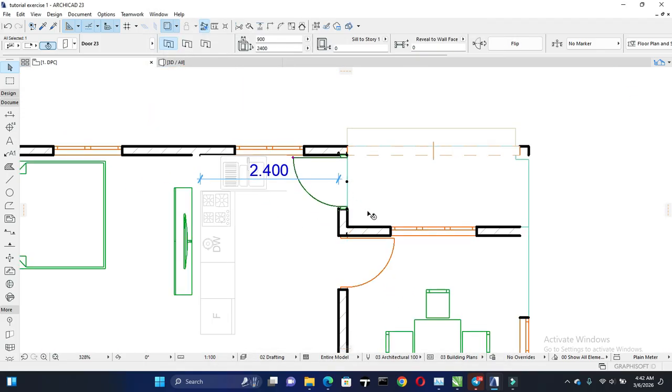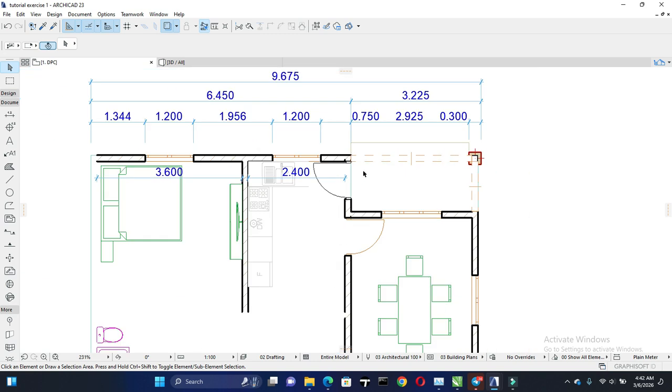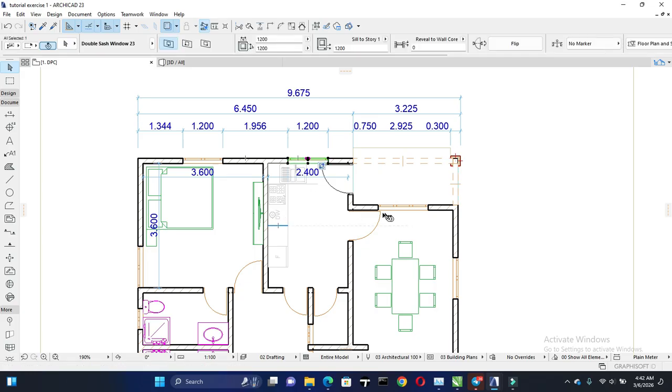So now that you've done settings for one, you could pick the parameters and inject them in all the doors. I'm only giving you an instance. You could do the same for windows. Don't make the mistake of selecting a window and a door and hoping to get the same settings, or trying to inject the parameters of a door on a window, or vice versa, or on any other components, because it will only change the components to the source components. I hope that is understood.